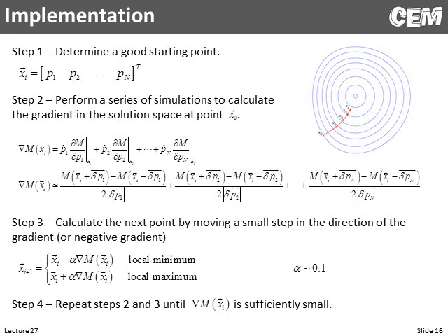And then when I call my merit function calculator, the first thing I'll do in there is take all those numbers that go from 0 to 1, and convert them over to numbers that actually make sense to the device, like duty cycle, grating depth, grating period, and stuff like that. But we start off with a starting point, with some position in our solution space. These are our design parameters that tell us everything we need to know about our design in order to calculate how well it works.